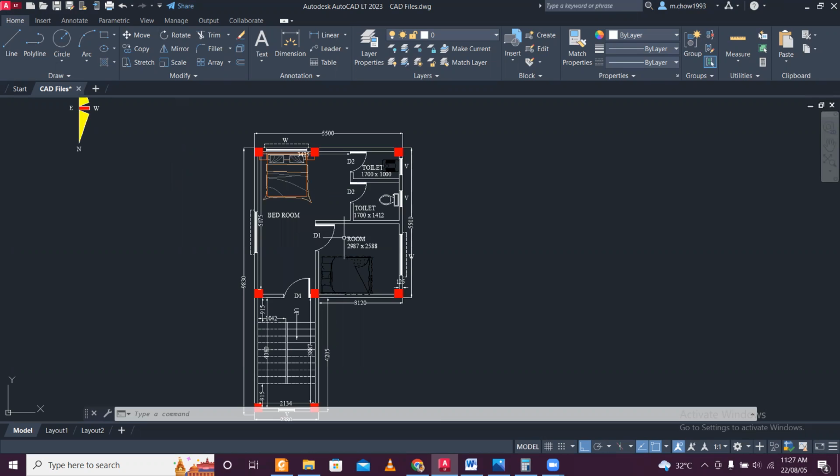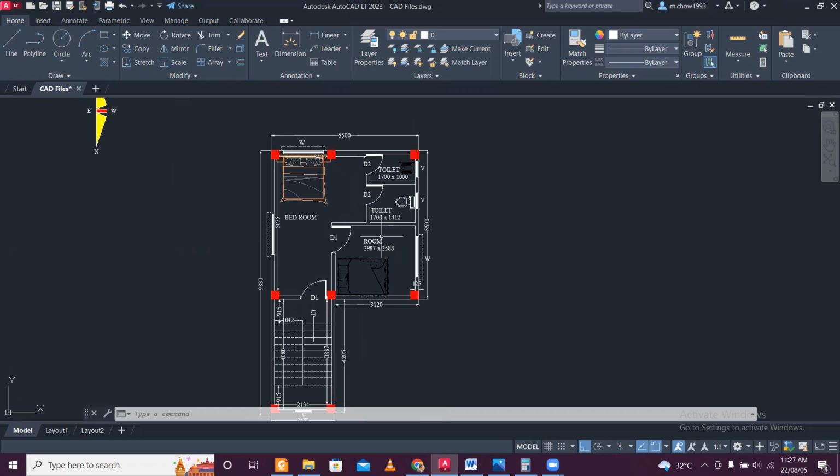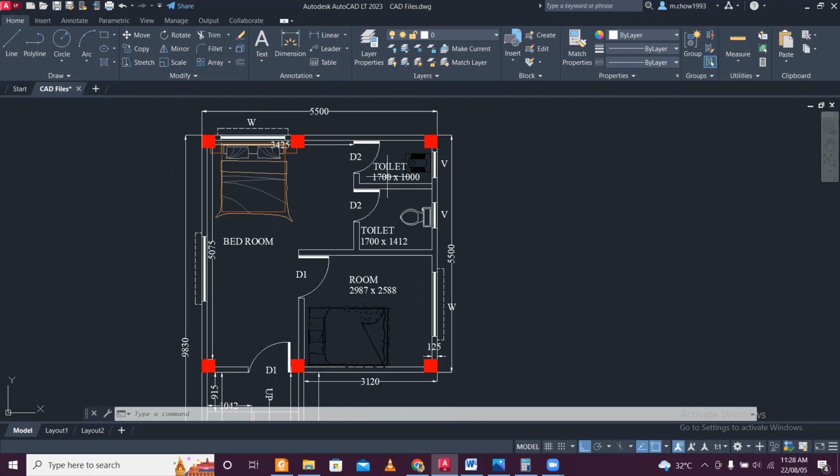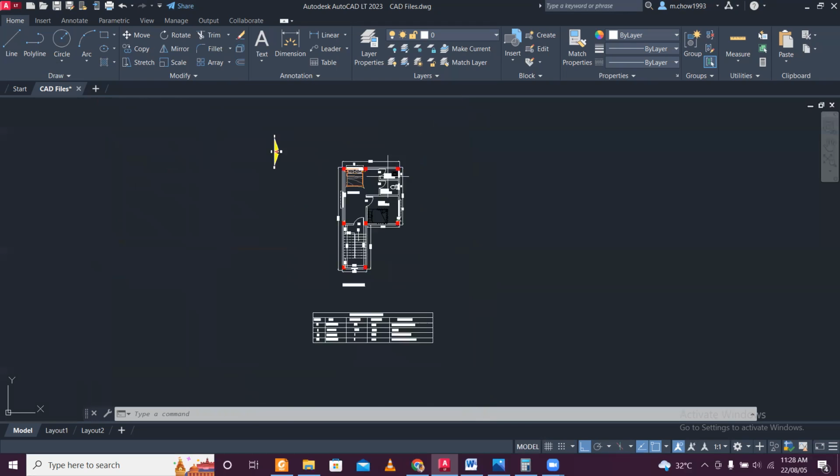So now moving back to the video, we will make a building design in STAAD from a CAD file, A to Z process. We will mention here this is a G+1 building. Now as you can see, this drawing is in mm. First thing you need to do if you want to import it is make the file in meters, right? You need to make the file in meters.